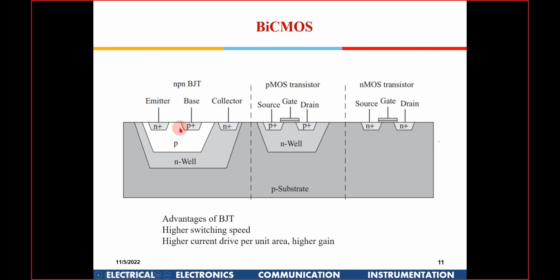Okay, so how does a BJT work? Initially, if you don't give any voltage to the base, you have N, P and N, and if you give a positive voltage to the collector, this PN junction will be reverse biased, and there will be no current flowing. But when you give a small positive voltage to the base, electrons will be attracted from the emitter into this region.